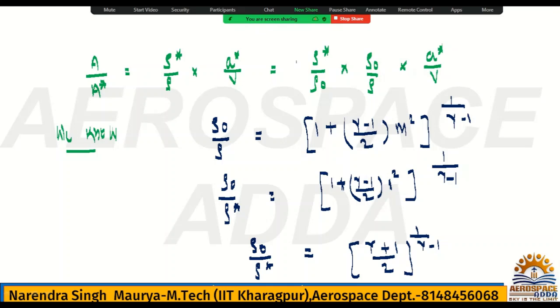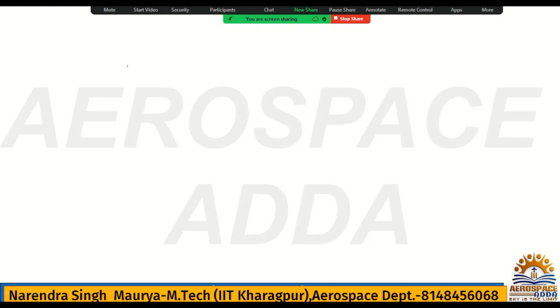Now this one result, rho naught by rho star. Now you can get rho naught by rho, which is the isentropic relation basically, and rho naught by rho star, both values you achieved here. See, you can keep it here. Now what about A star by V? How to get it? This is simple. I can write M star, which is called, sorry, not critical, characteristics Mach number.